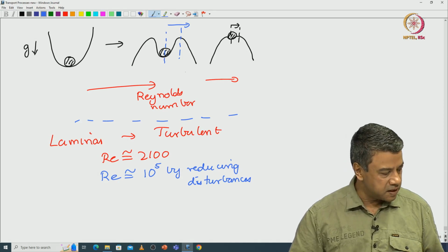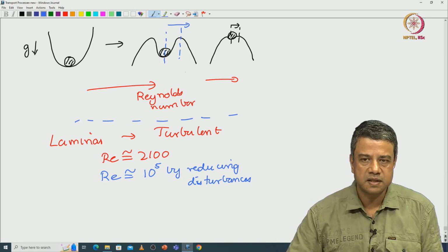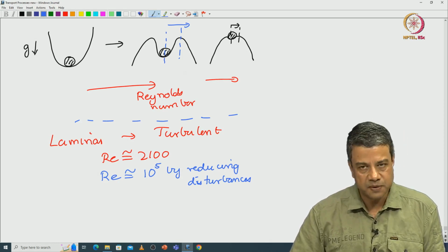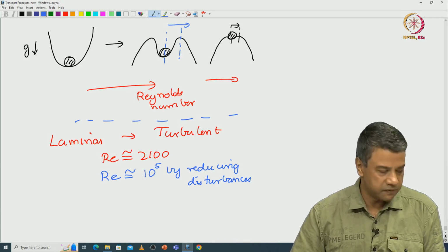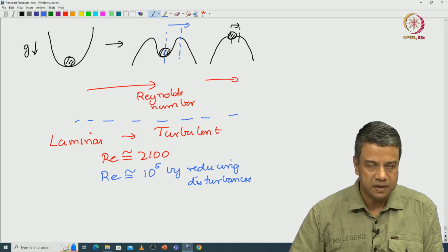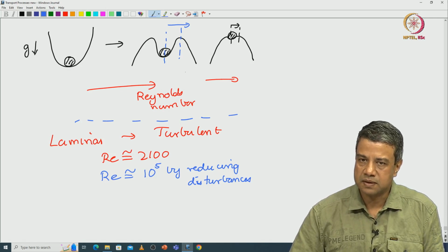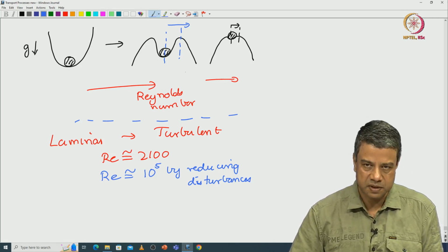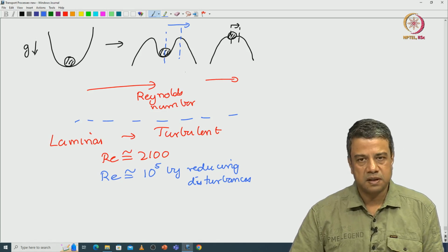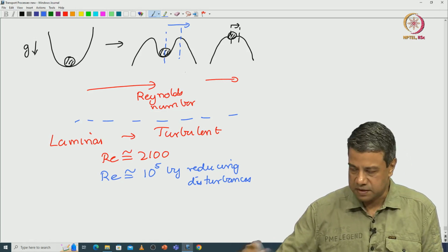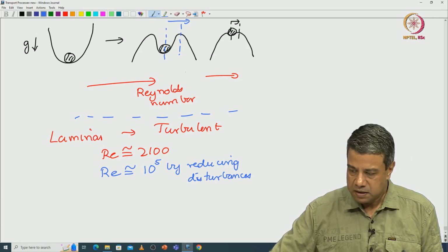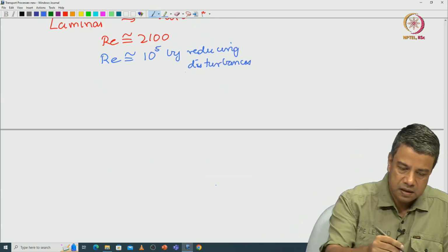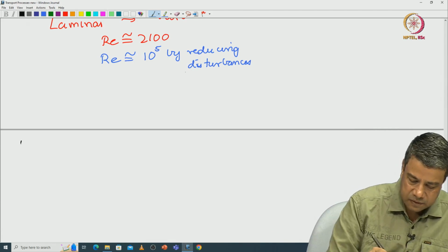And we had also discussed how the fluid velocity is separated into its mean and the fluctuating parts, and dispersion due to the fluid fluctuating velocities. If you recall, we discussed the Reynolds stress as well as the Reynolds fluxes, when we had talked about dispersion. That dispersion in this case is due to the fluid velocity fluctuations. So, let me tell you some characteristics of turbulent flows.